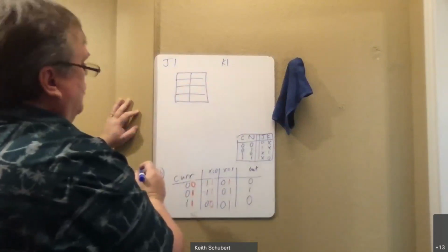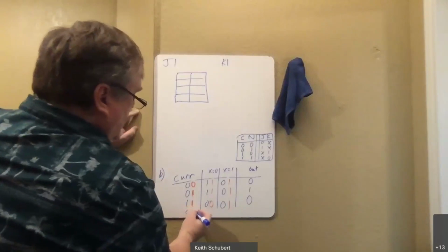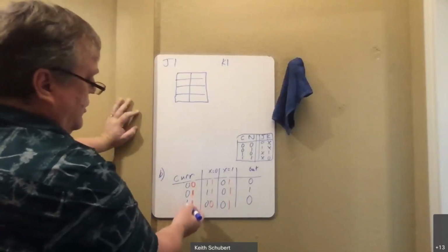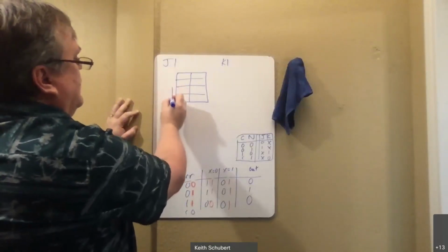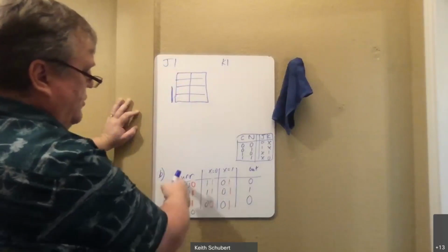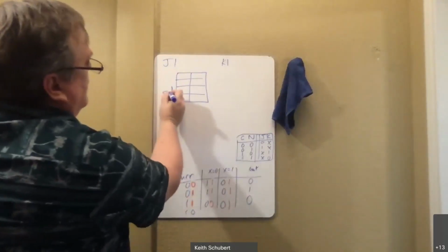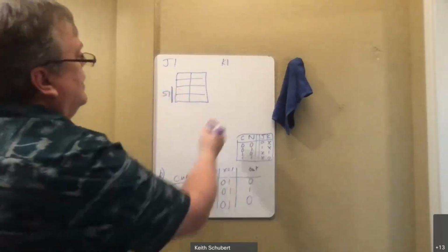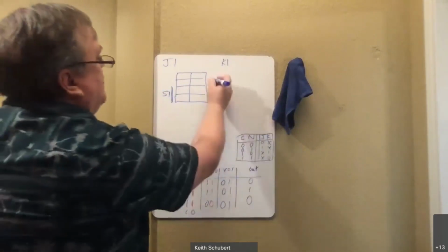When I make my Karnaugh maps, I've got the 1, 0 here. So this bit, which covers this side here, is the most significant bit of my current state. So this is state bit 1. And the middle one, where they're both 1 here, that's the least significant bit.